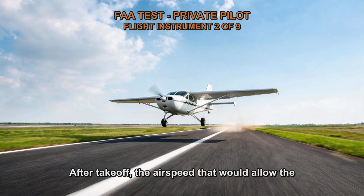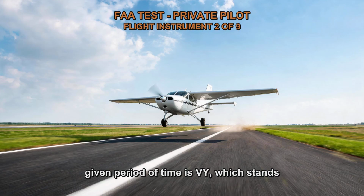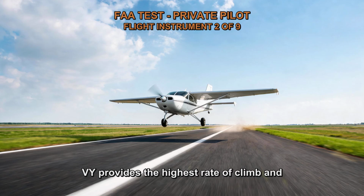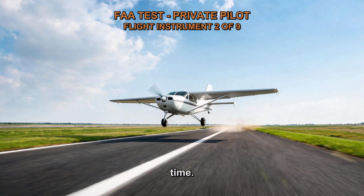After takeoff, the airspeed that would allow the pilot to gain the most altitude in a given period of time is Vy, which stands for best rate of climb speed. Vy provides the highest rate of climb and allows the aircraft to ascend most efficiently in terms of vertical distance gained per unit of time.